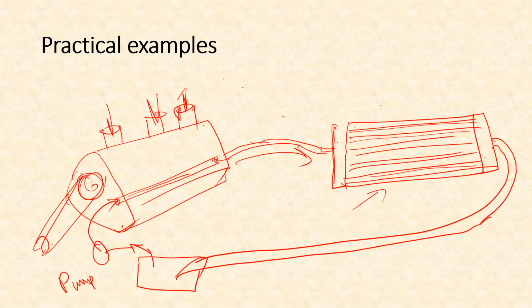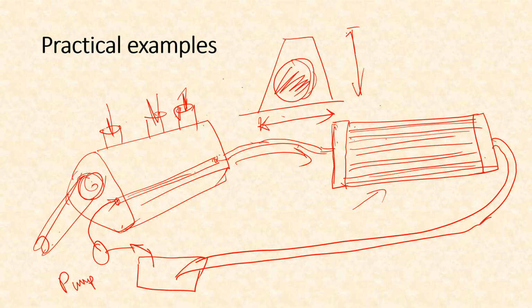And the same is also done in case of large dam construction, because as we know, dams are very huge, and when they are made of concrete, since setting of concrete is an exothermic reaction, that means if we have a very large dam like this, which is suppose 50 meters across and 60 meters tall, the inside of the dam, when you pour the concrete, then during the setting, that heat will be generated, and if the heat generated cannot escape, then it will expand and the entire dam may crack.